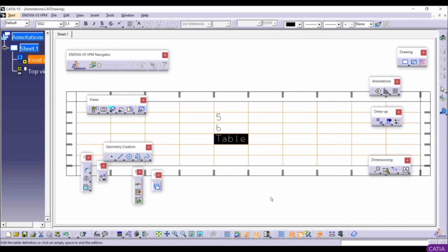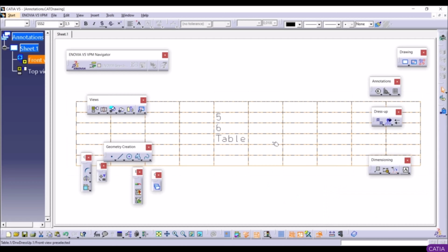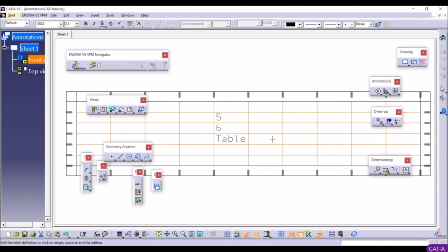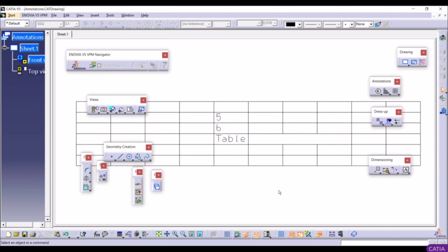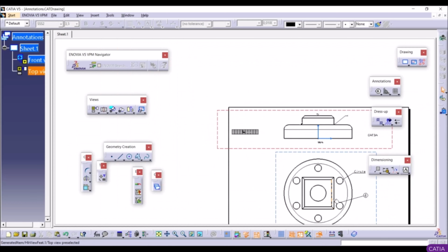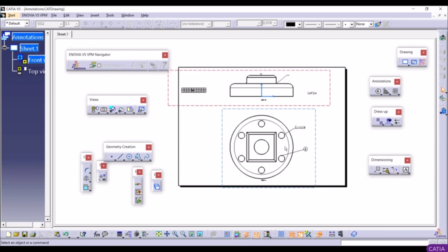Let's go with OK. You also have an option, let's double click here, to merge some cells. So you can select those cells, right click, you can go with merge. And now those 3 cells are merged together. Let's click outside, like this, double click. And this is our table. So this is how you can create text, symbols, and table in the Catia.